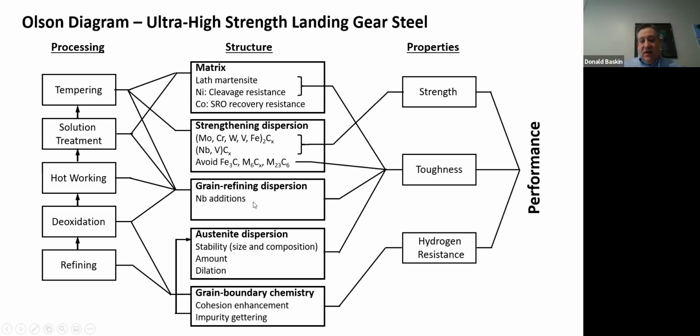We talked about strengthening via the Hall-Petch relationship, where you minimize the grain size because the strength of this steel, for example, could be an aluminum as well, nickel, goes inversely proportional with the square root of the grain size. That's called the Hall-Petch strengthening. Niobium, as I mentioned previously, is a very potent method to keep grain sizes small. And a lot of steel manufacturers use niobium to make sure that the grain stays small, or the word they use is refine the grain size and keep it that way long enough to use the material before it gets too hot and maybe grows. But hopefully it doesn't get that hot. We talked about an example there with aluminum and the motor housing.